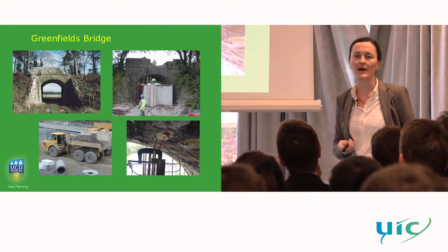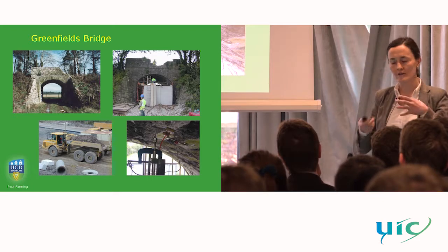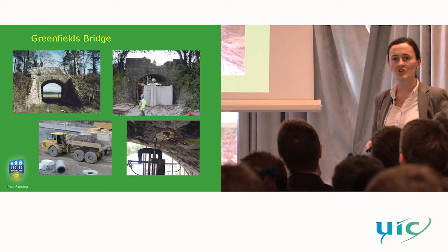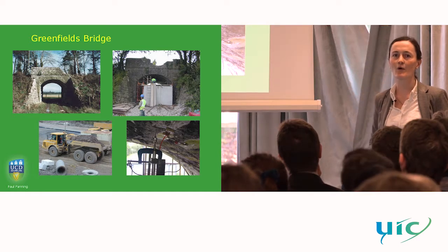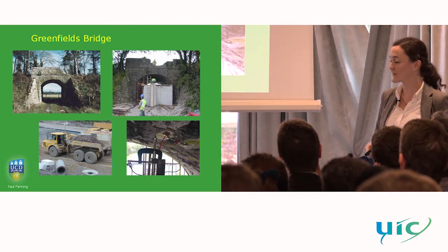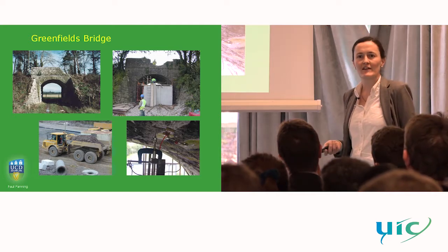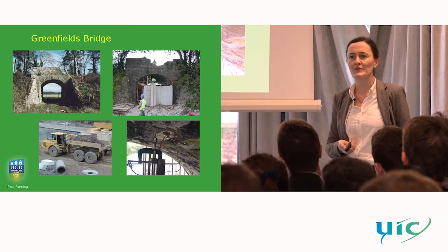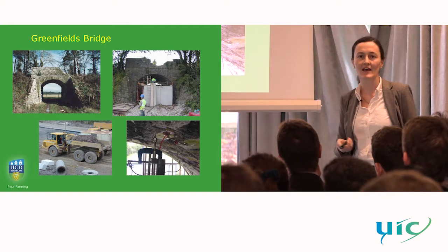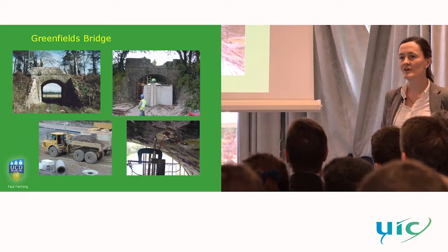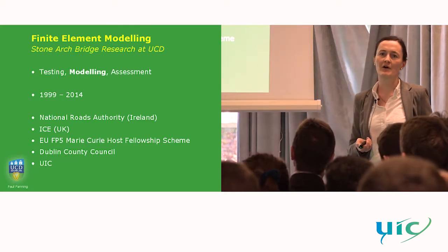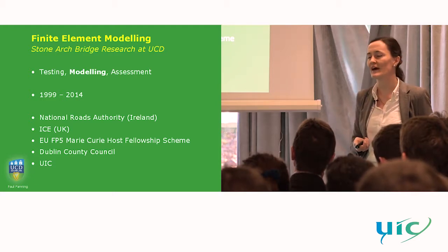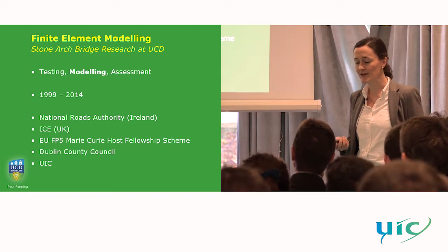So this was tested up as high as an 80-ton single patch load. So in addition to the service levels of loading that we had to validate our models, we also had one example of high-level load tests as well. And we've also tried to validate our models against very simple things that are easily available, like crack patterns. And essentially, the aim with the modeling has been to build up a fairly uniform approach to modeling arch bridges three-dimensionally.